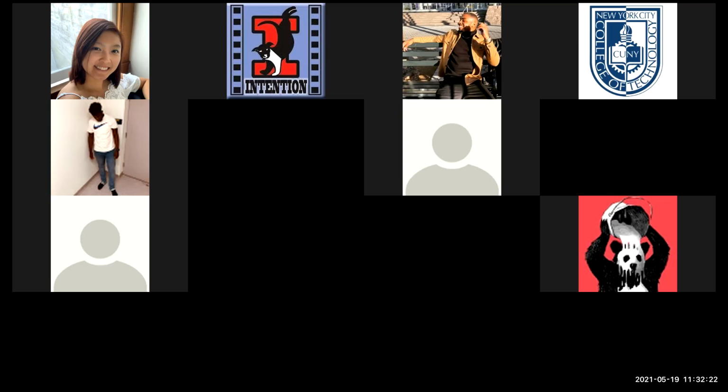You still got to say who you are, when this was drawn, what scale it is, what was drawn, what the project is. You've got to have the same information, but it's just arranged differently. Right, because they look at the title blocks specifically for that information. Oh yeah, you have to have the scale and so forth. But what the title box looks like, that's up to you.